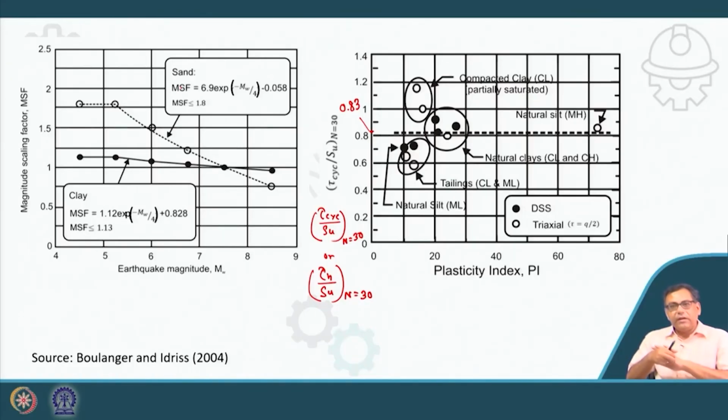But you can use these magnitude scaling factors for sand-like material during liquefaction check also. If you follow the procedure that I have given, which was published in 2001 as the summary report of those two workshops, then you should use that range of recommended MSF, and I will also use that range.